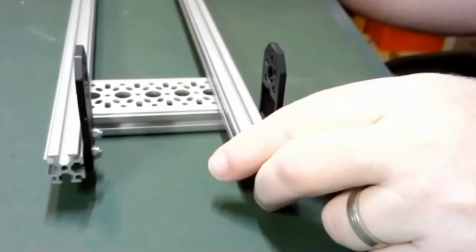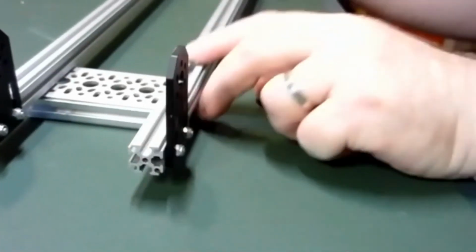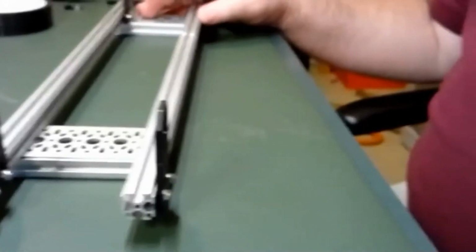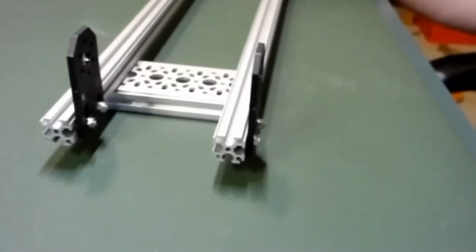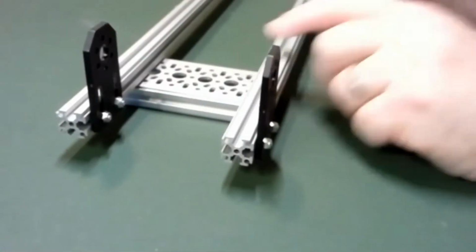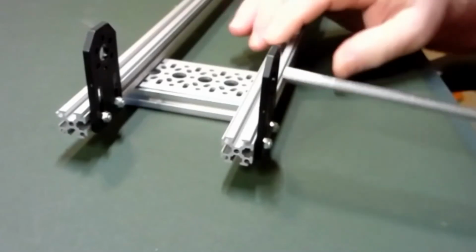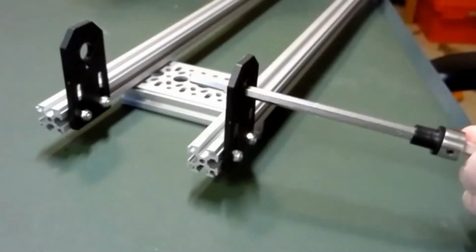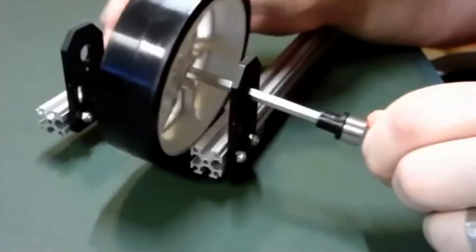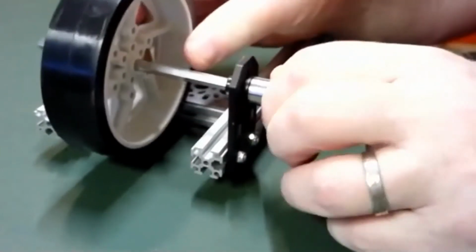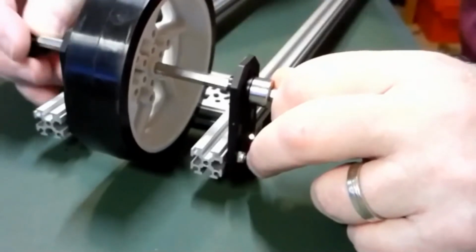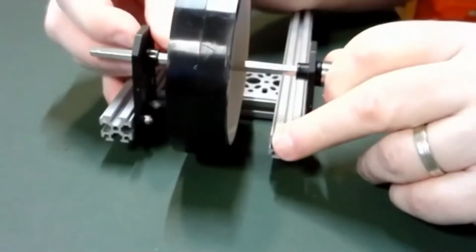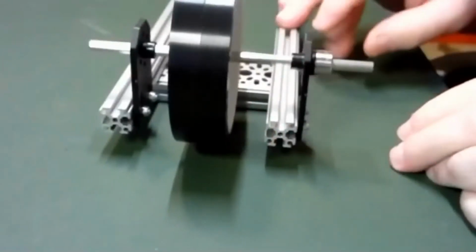And the idea behind the motion brackets is they act like the pillow blocks do, but they allow you to extend away from the extrusion a bit more. And so here's the motion brackets. And then you can take a shaft and you can put the shaft through the motion bracket. This shaft has a bearing on it right here. So you can take the shaft, go through the motion bracket, go through your wheel, go through the other motion bracket that's there, put a bearing on the other side, and I'm not going to bother to do it, but if I could put a collar on the other side, and that's what enables this wheel to be on those motion brackets and enables it to spin.